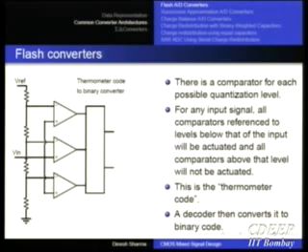You may say that all right, 256 converters, so what? I'll produce any number of comparators that you want, but I want a very fast converter. But there is a limit to speed as well because of this loading aspect. Your driver will have a finite output impedance, and R times 2 to the power n C, where C is the input capacitance of each comparator, will come across this. And as you add a bit, this capacitance actually doubles every time, becomes quite substantial. Therefore, you will start hitting a point where there is no point in trying to improve the accuracy of this.